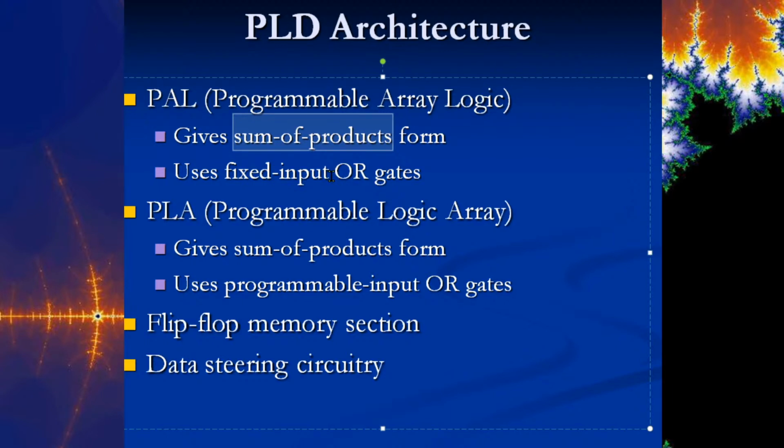It would be AB plus CD plus EF, the sum of products. Okay, a programmable logic array, if it's backwards like that, it's a sum of products. Both of these are sum of products form. If it was product of sums, which will become relevant in chapter 5, I apologize, when we talk about that in chapter 5, it's going to be the opposite.